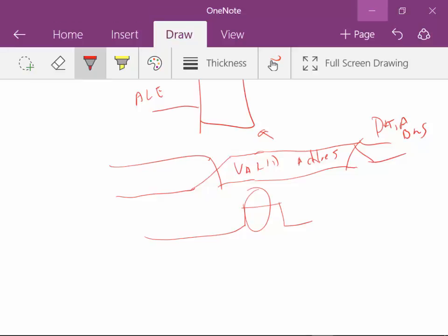So all we're doing with an address latch, either gated or using a clock, is controlling when we latch that data. Because once we latch this data at this point, it's no longer an address bus. The microprocessor is free to change that data to wherever it wants, and the memory address lines are still the address lines. Then we can use the same lines out of the microprocessor for moving data in and out. The reason we do that is to save real estate on the board and real estate on the microprocessor as far as the number of pins.